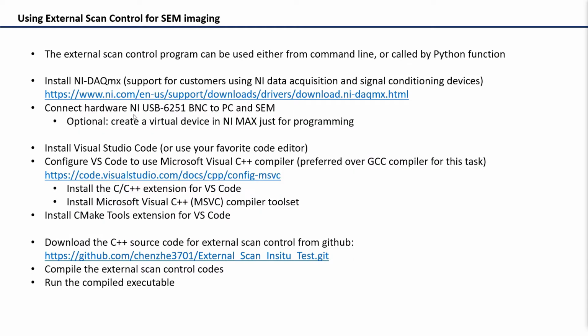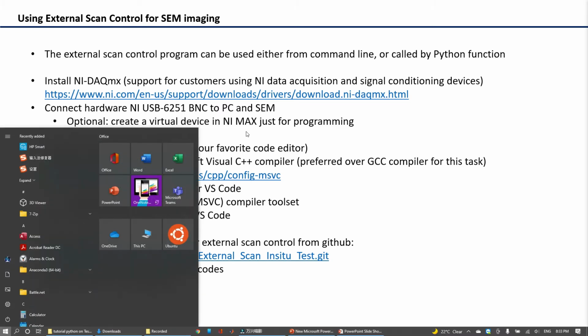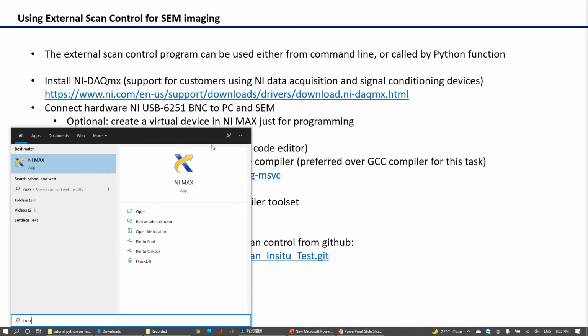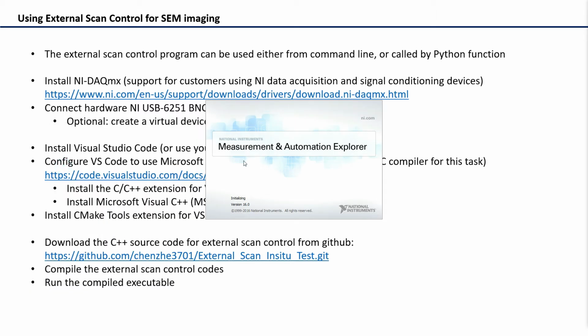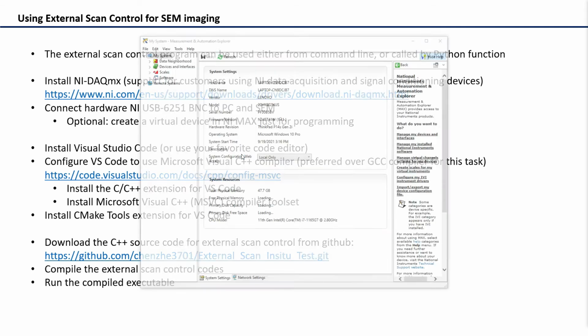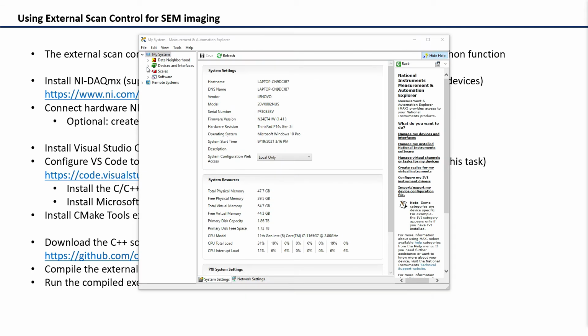After installing the driver, when you plug in your device to your PC, the device should be recognized, and then you should be able to use the device. Optionally, you can create a virtual device in NI MAX, which is the software installed with the driver, for the purpose of debugging, so that you don't have to physically connect to the device for programming.